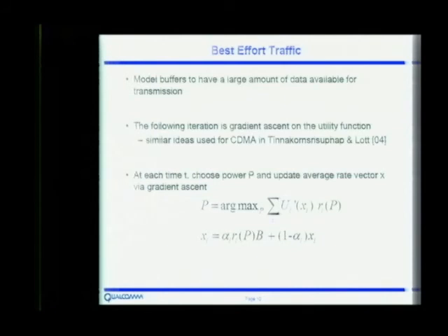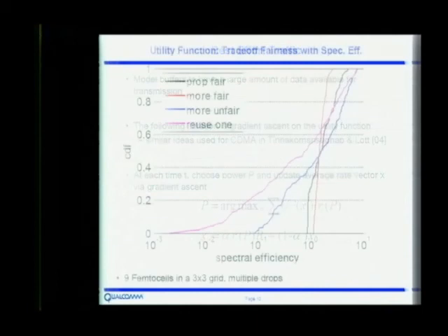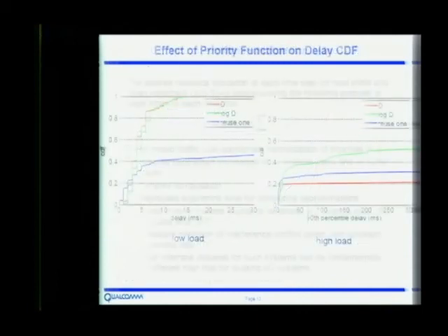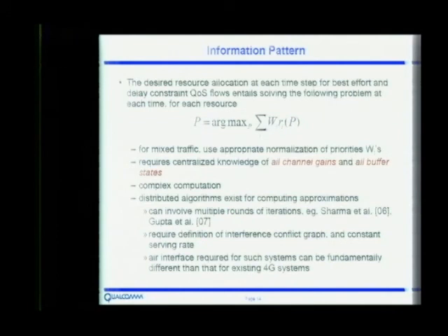So when you say centralized information, is it one base station or multiple base stations? Let's say we're looking at 10 clusters, 10 femtocells in a building. You would need to know the channel gain matrix, a 10 by 10 channel gain matrix, so the interference from each of these pairs of cells. So it's centralized across your choice of the subset of the femtocells in the environment. You choose these 10 cells that you want to control, so you would have to be centralized across these transfers.